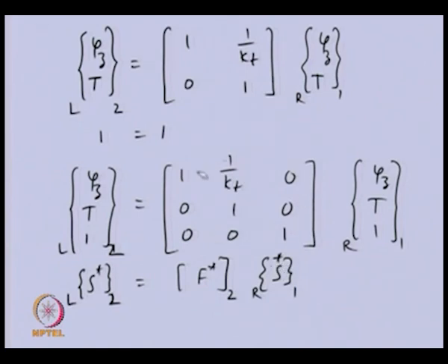The only thing is the size of the field matrix is 3 by 3 to accommodate the torque inside the point matrix, but you can see that the overall form is similar to the free vibration case. So, now we have developed the basic point matrix and field matrix corresponding to the disk and the shaft respectively. Now, we can use these for obtaining the natural frequency or forced vibration for any rotor system. So, now through one example we will see how these can be used.